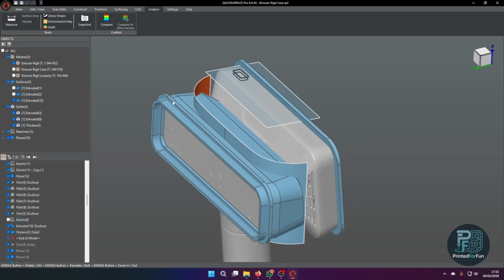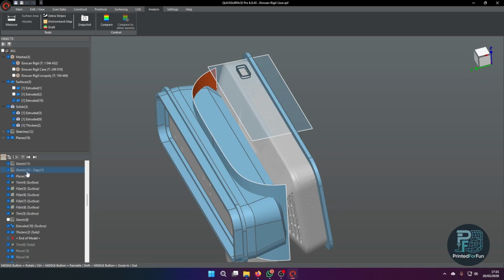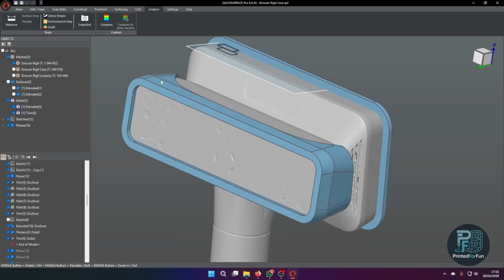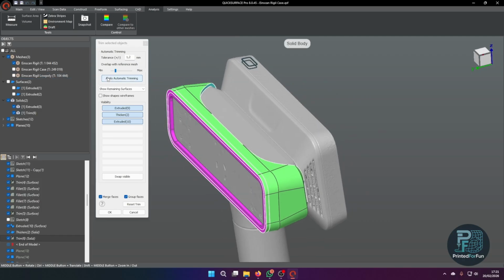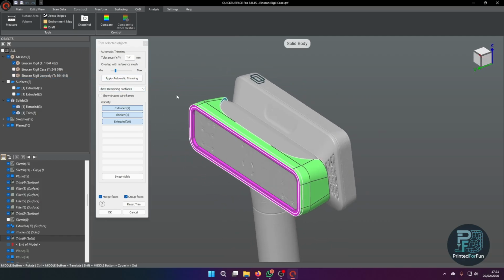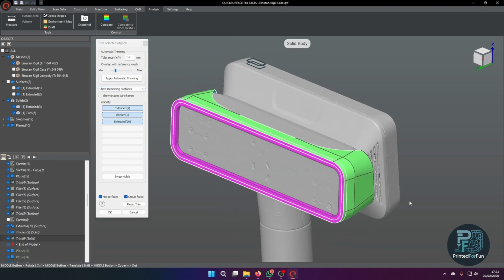And now the next step: we have this top protective sleeve, and now the sleeve and the surface I can just trim down to one part. And here in the trimming, there's one thing I initially didn't know. Currently you're seeing all the remaining surfaces or the remaining bodies. And it even shows me, okay, it's a solid body. So I can just click OK.